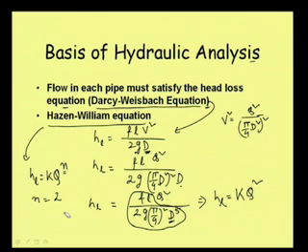So for practical purposes we can assume this as 2, because if we consider the head loss to be on the higher side, so far as distribution is concerned we will be on the safer side. So we consider that n is equal to 2, then it becomes HL equal to KQ square. And this expression is generally used.